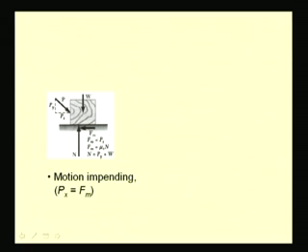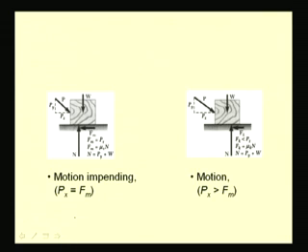So, one has to be careful in solving equilibrium problems with friction: only if the motion is impending, we can use this relation between the horizontal force F and n using the coefficient of friction. If we are not sure whether the motion is impending, then this relation cannot be used. And when the body is in motion, this force Fk is less than the force that causes motion, that is Px, and this force is equal to mu k times n.